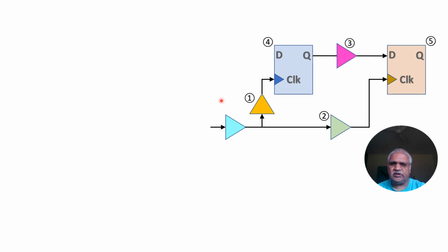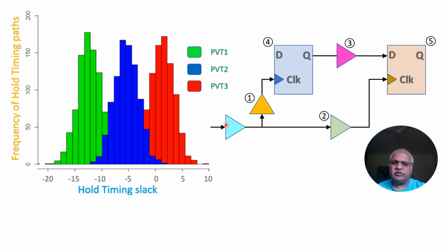In a normal soft design environment, these elements will be in different configurations. Since they are different, even if we take PVT3 as the slow corner, there will be some timing paths which will be slightly failing. As I showed earlier, this is one typical scenario. Sometimes the overlap may be on this side, so you will see some failures here even in the PVT3.